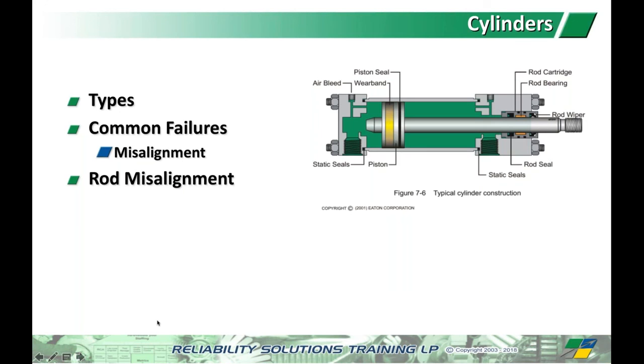So when you hear the normal operation of that thing as it extends and retracts, it's a pretty quiet thing. And we're listening right now. We've got the contact probe right here, right above the seal, where we're trying to listen to some point of contact. Sometimes you may have a cushion in there. That's probably not the best spot. You really want to be right here on the seal, or even on the wiper if you can get to it.